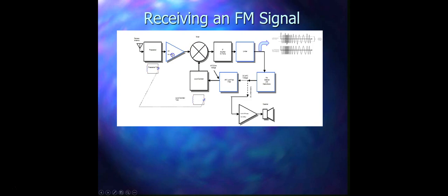Now the second purpose of this RF amplifier is local oscillator energy separation. In the local oscillator, the power levels are between 0 dB and 10 dB, which is very small. So what would happen if the local oscillator output gets coupled to an antenna? In that situation, your receiver would basically behave as a transmitter. The receiver can then become quite a potent interference source, and that's the reason we use a radio frequency amplifier, which prevents local oscillator re-radiation by allowing the signal to flow only in one direction, from the antenna to the mixer.